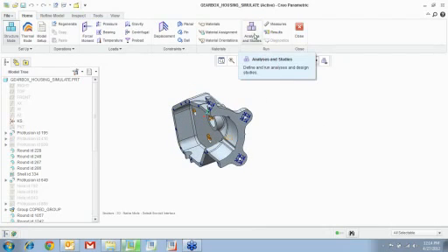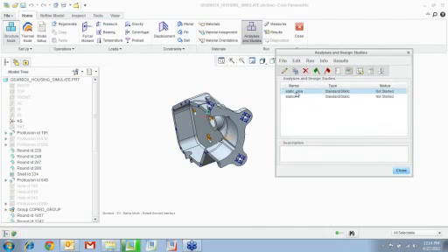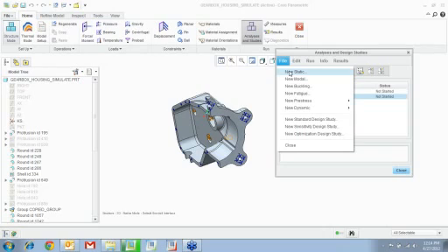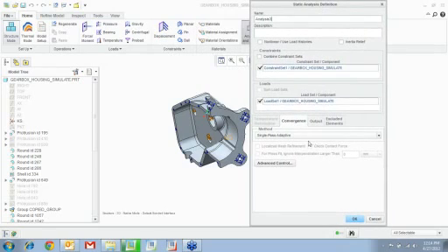Now that's one thing. Next thing is when you run the analysis, I've done 2 passes right here and I'll explain what these are. So I'm going to go File, New Static. In here, note that you can choose multi-pass or a single pass or a quick check. Now, what is the difference between multi-pass and single pass? Let's get through the passes first, and then we'll discuss the differences between them. As of now, I'm going to choose a single pass.